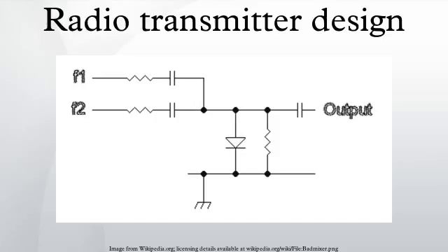Variable frequency systems. An array of crystals used to enable a transmitter to be used on several different frequencies. Rather than being a truly variable frequency system, it is a system which is fixed to several different frequencies. Other options are the variable frequency oscillator, phase lock loop frequency synthesizer, and direct digital synthesis.